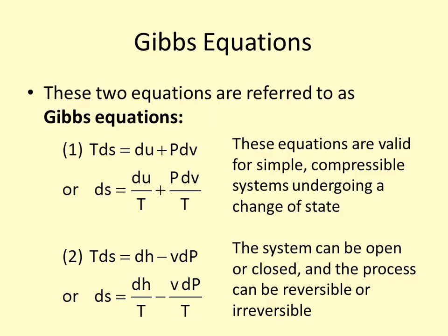So if we find that there's a huge pressure drop and that's contributing to the change in entropy, then we may need to change something about our system and minimize the pressure drop. Of course, analyzing the other pieces, the other equations, the energy balance, mass balance, etc., we can see whether the trade-offs that we make in playing around with these property values are worth it or not financially for our system.